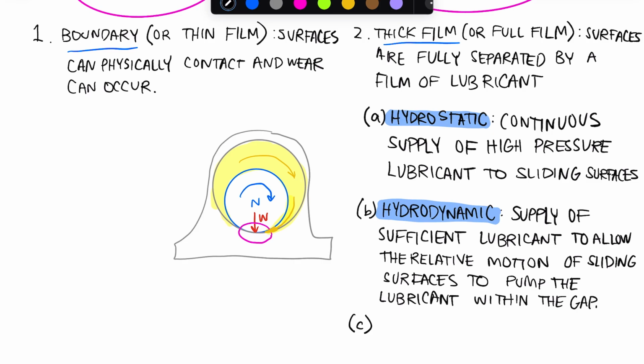All right, and then last but not least, we have elastohydrodynamic lubrication. This is similar to hydrodynamic lubrication with one additional step: the pumping of the lubricant within the gap actually causes elastic deformation of the surfaces sliding against one another.